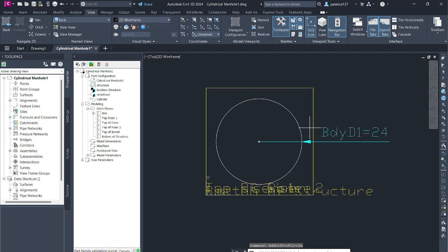Move your cursor to become active in the SCH column, and then click the Edit button from the Edit Part Sizes dialog box toolbar. The Edit Values dialog box is displayed. Click Add to add the following values: 0, 6, 12, 18. Click OK to exit the dialog box. A list of values is now available for SCH.